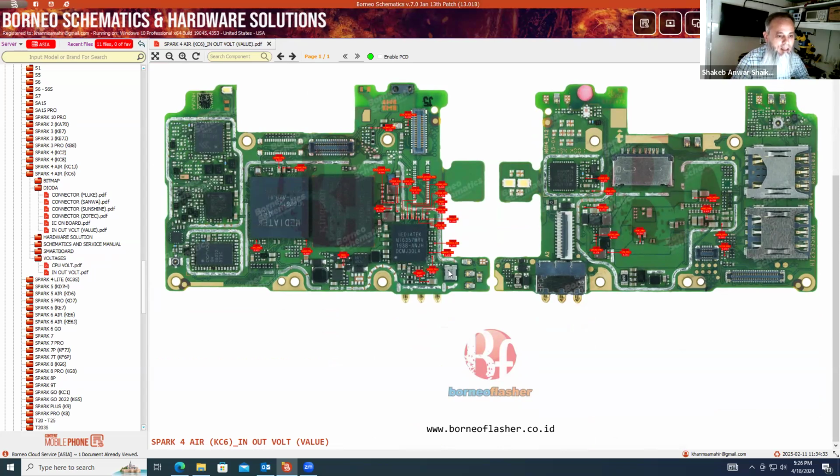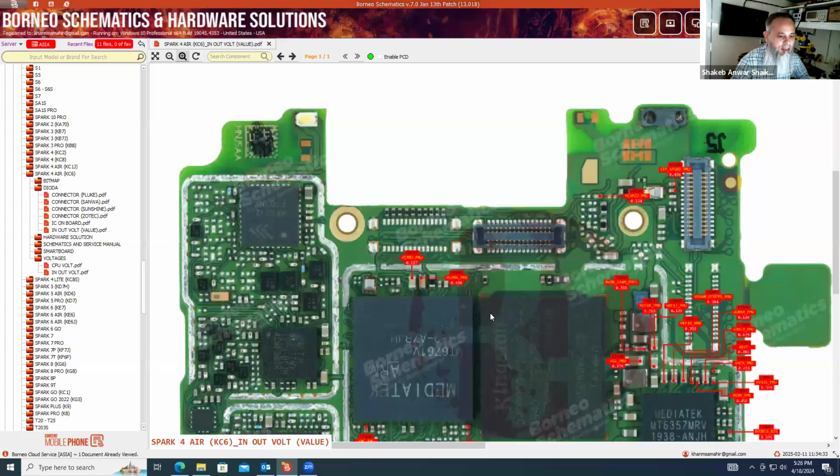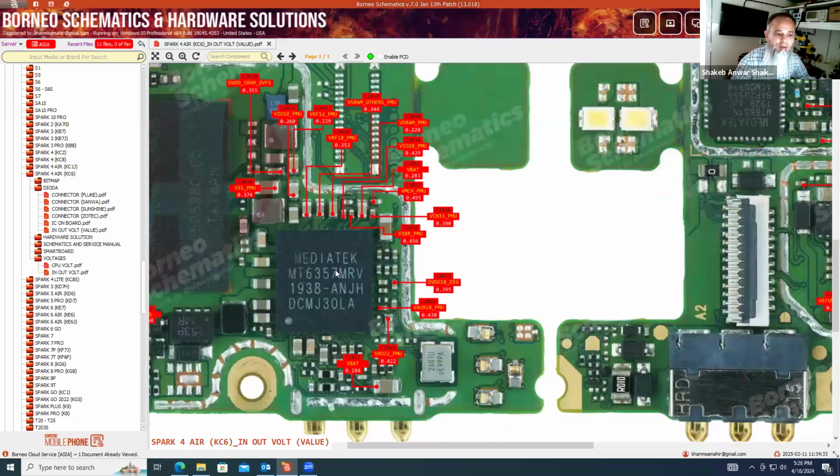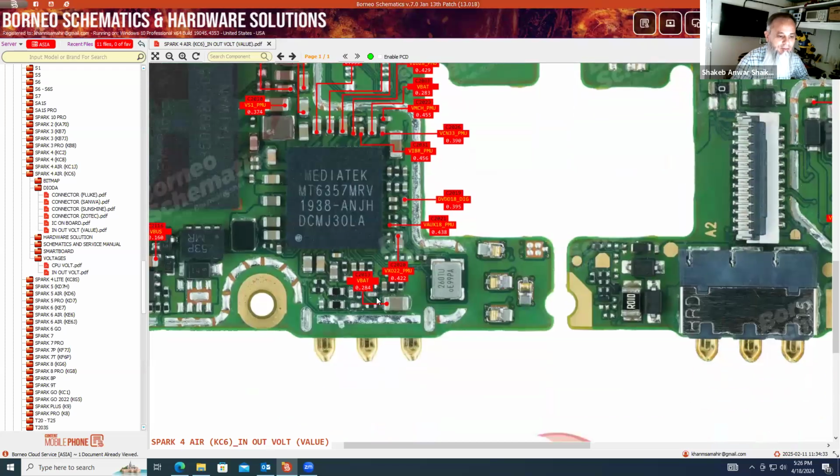Now in the PM, when you power on your mobile phone, in hot testing, you take your multimeter, take the negative probe and put it on the ground line. So negative will come over here. With the help of the red probe, you should be able to get this particular VBAT.